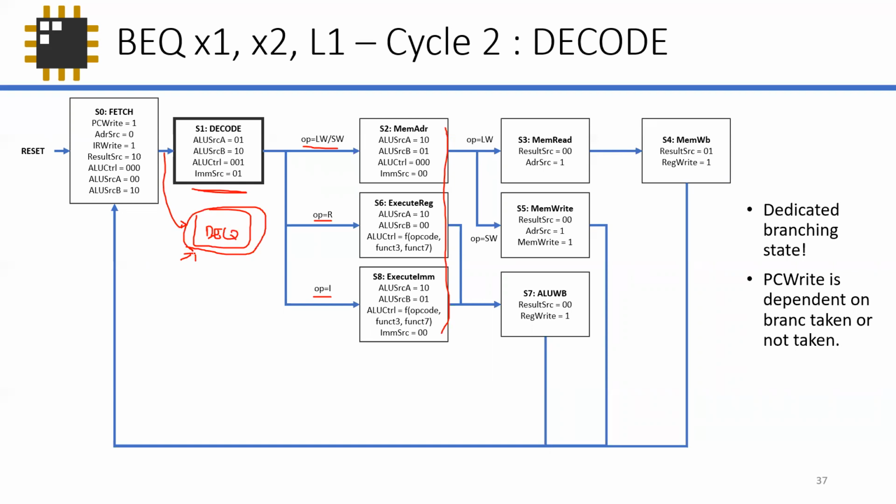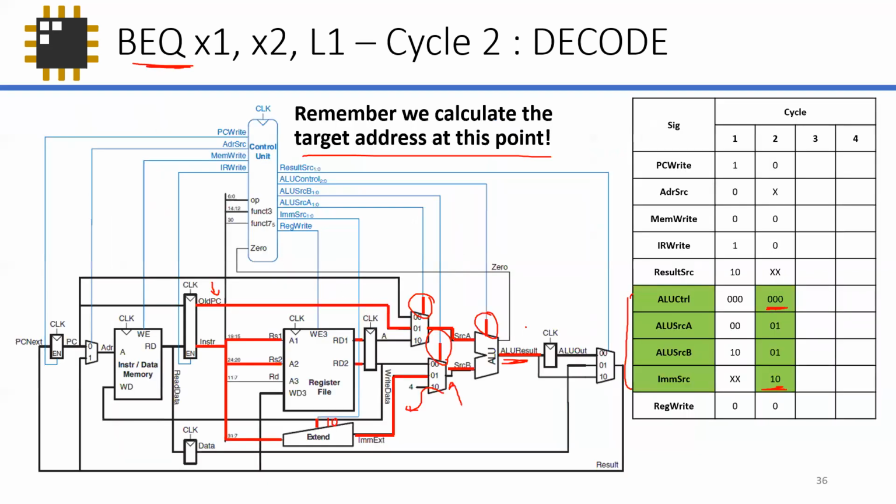So we have this clever idea: since the ALU is not being used, why don't you just put it in the decode stage? In the event that you do a load word or register or immediate type, it doesn't matter. If you compute it in the decode stage and it computes some target address here, even if it's some dubious or erroneous data that doesn't make sense.